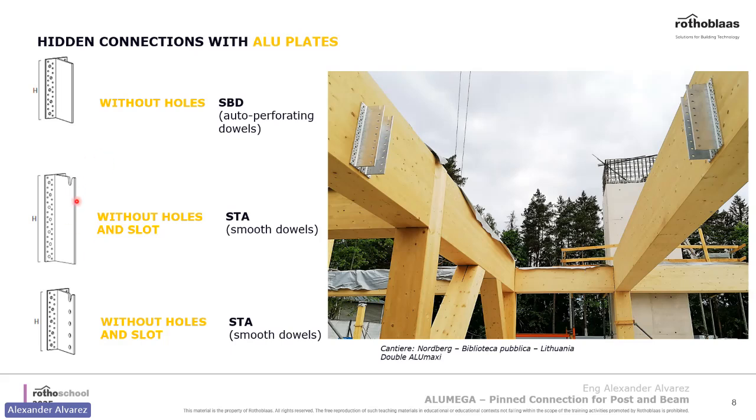This one doesn't have any holes, so what you can do is just connect the beam, slide the beam in, and make your holes, spacing them out. You can add as many dowels as you want, obviously making sure you respect the distance between each hole, so that you're not creating cracks in the beam.